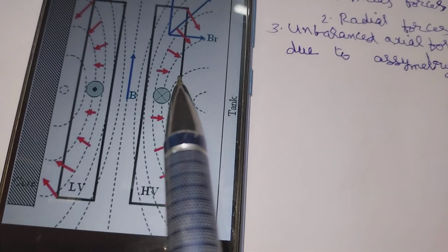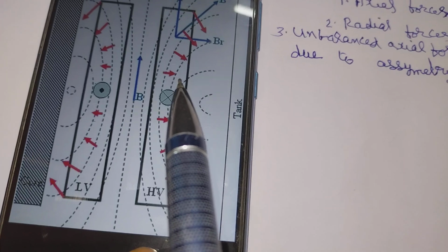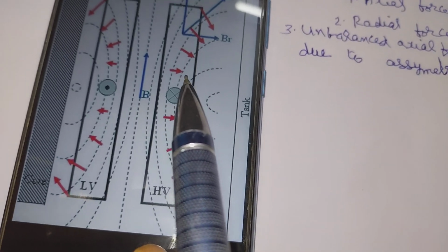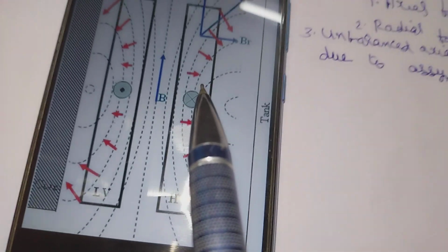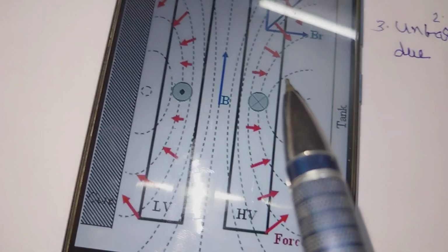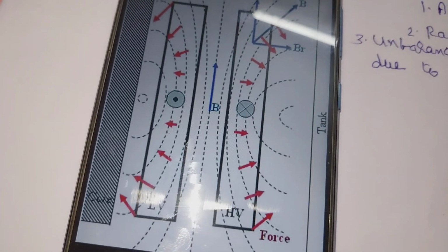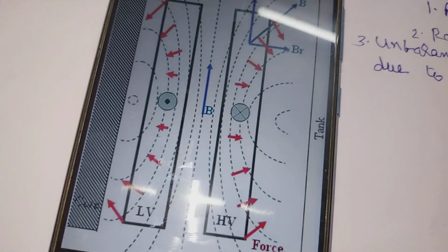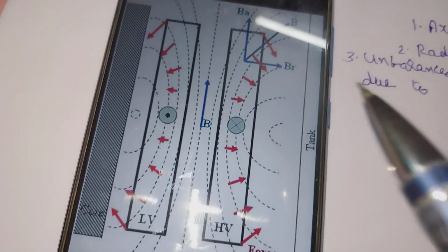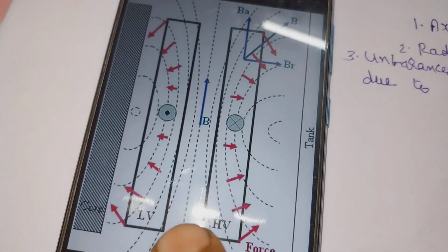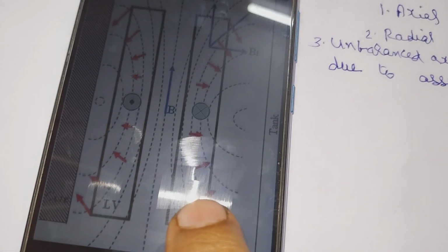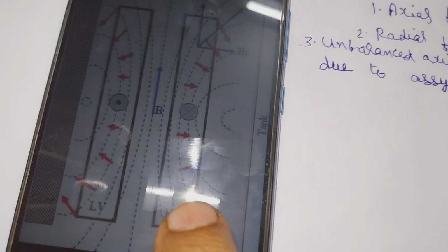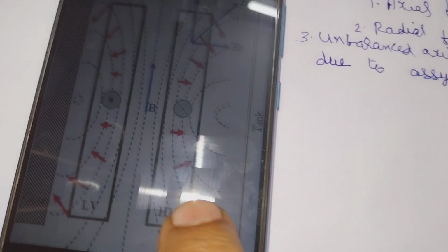This is obvious because the two windings carry currents in opposite directions and hence produce repulsive force tending to pull the outer winding and to compress the inner winding of the transformer. It is clear that circular coils should be preferred, as they are the strongest to withstand these forces.